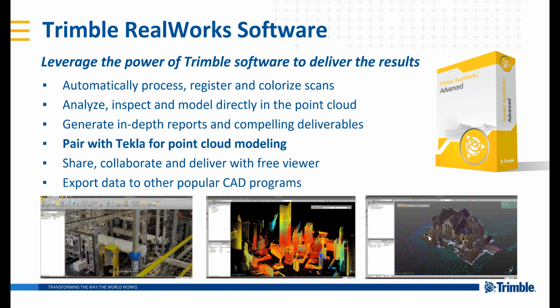Depending upon the size of area that you need to scan, more than likely you're going to have to take more than one scan. Each scan is like a piece to a puzzle, and the way that we assemble that puzzle is by using a software called Trimble RealWorks. This allows us to process and register the scans. We can analyze and inspect the model directly within the point cloud. We can generate reports and other type of deliverables.